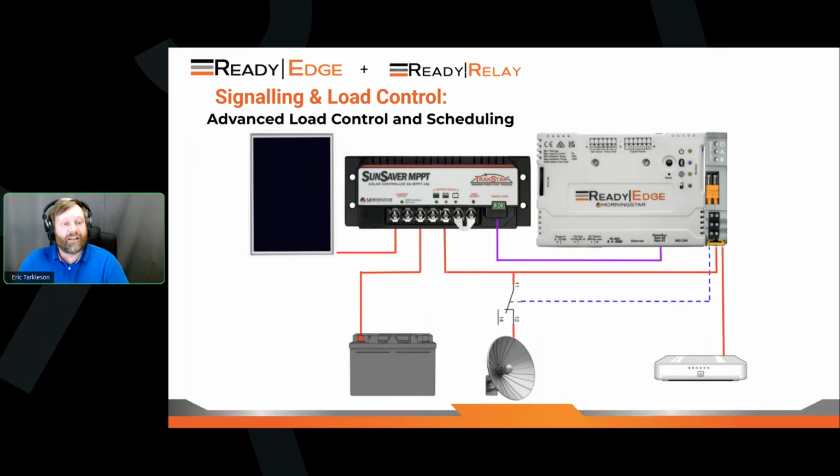And then again, let's talk about some of the load control and scheduling options. So again, we're using the ReadyRelay. In this case, we're using both of its channels. And what we're going to do here with this application is we're going to use our satellite comms, and we're going to turn that off if the battery voltage gets too low. So if it's a lead acid battery, maybe below 50%, we're going to turn that off. So we've implemented low voltage control directly through the ReadyEdge.